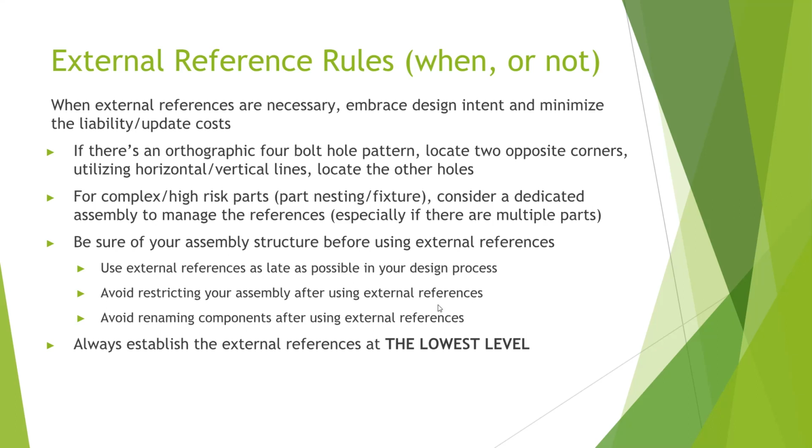Avoid restructuring your assembly, right? Before you start heavily using references, don't be taking parts and dragging and dropping them up among your assembly tree, dropping them in different assemblies, because that breaks things. And renaming, SOLIDWORKS has come a long way with supporting rename, but it's still a risk and it still messes stuff up.